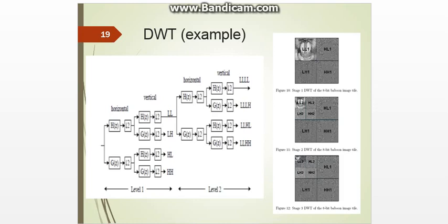The spatial domain data are transformed into the LL, that is horizontal low pass and vertical low pass; HL, that is horizontal high pass and vertical low pass; LH, horizontal low pass and vertical high pass; and HH, that is horizontal high pass and vertical high pass subband signals. In the frequency domain, in image coding, the Mallat structure is usually adopted, that is the LL subbands in each resolution can be further decomposed into 4 subbands.